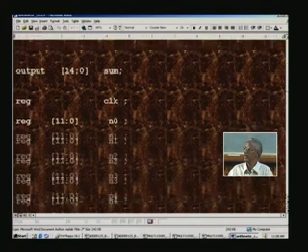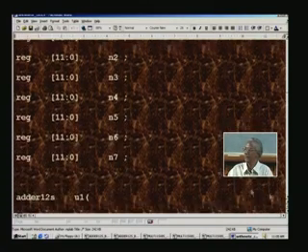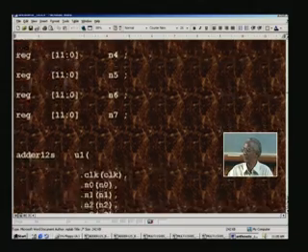Right now we do not want registration, and once again sum is declared, and all the inputs clock and N0 through N7 are declared as register in the test bench, and then we invoke the actual design, which is the adder, and instantiate here, and then list IOs.